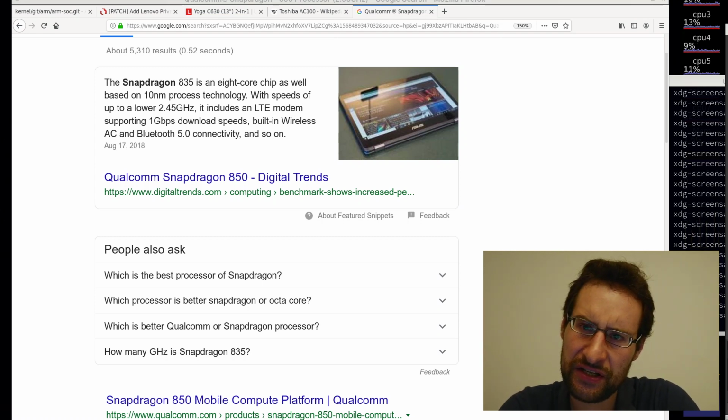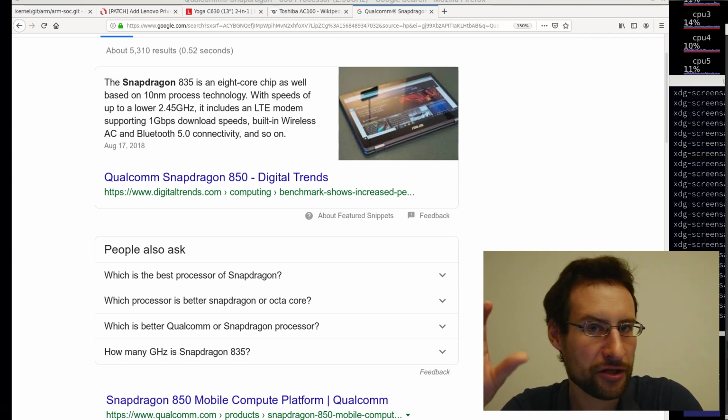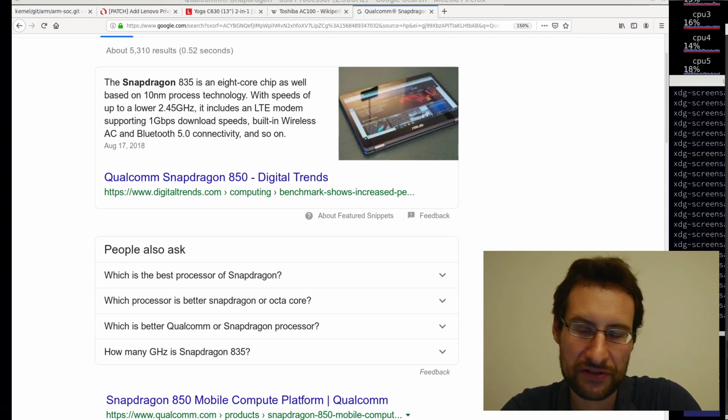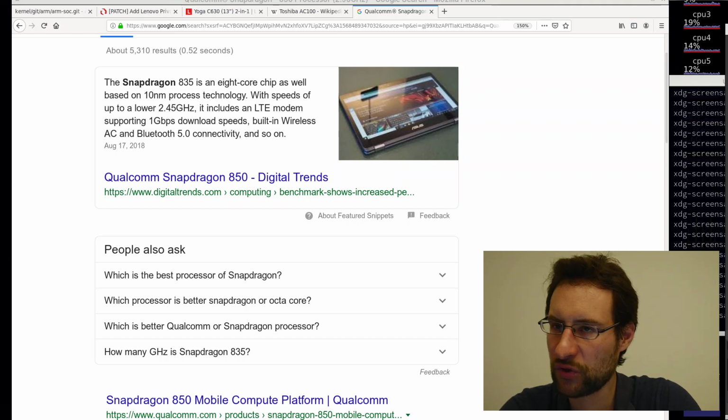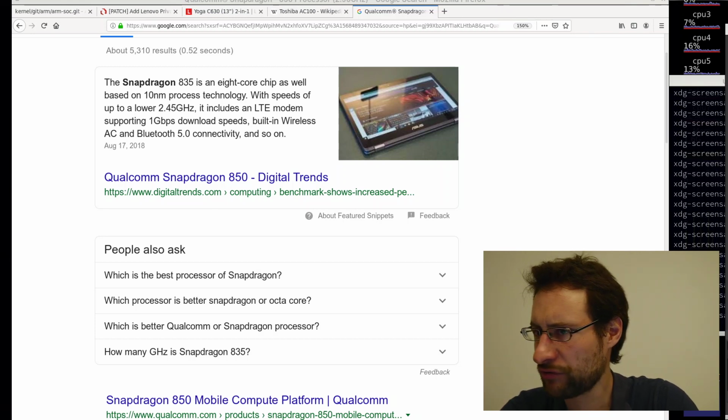By the way, I think the Raspberry Pi historically with the Broadcom has quite some firmware blob, right? I think it boots really strangely, as far as I once read and heard. I've not personally done this, but I think the Raspberry Pi Broadcom boots over the GPU, so it needs to load proprietary GPU firmware, and then somehow the GPU, like secure boot, boots the rest of the system.